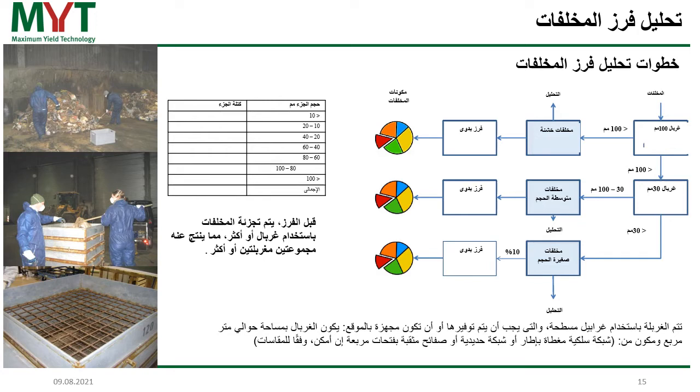The sieves must be available, or built on site, prior to the sorting analysis, and they can be built on site because it's quite easy. You need only about 1 square meter of a sieve. That could be a frame covered with wire mesh, iron mesh, or perforated plates with square holes if possible, according to the dimensions you want to have.